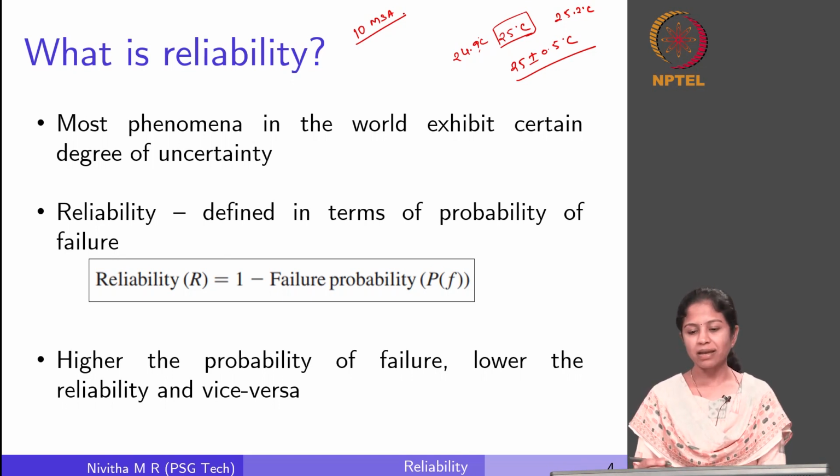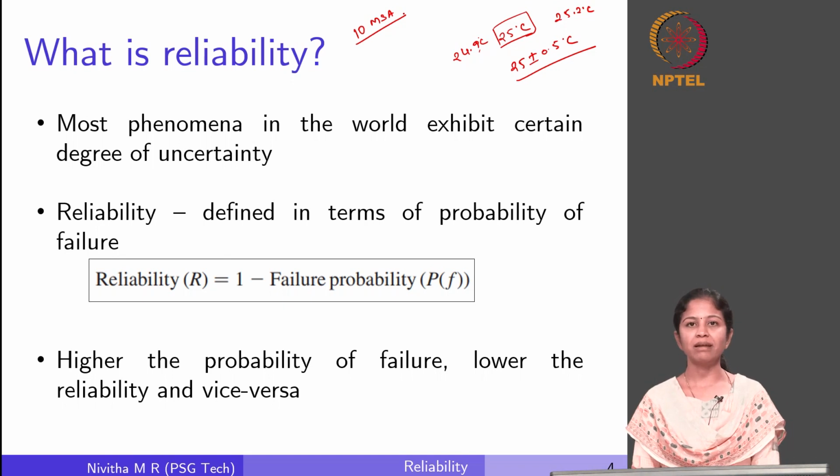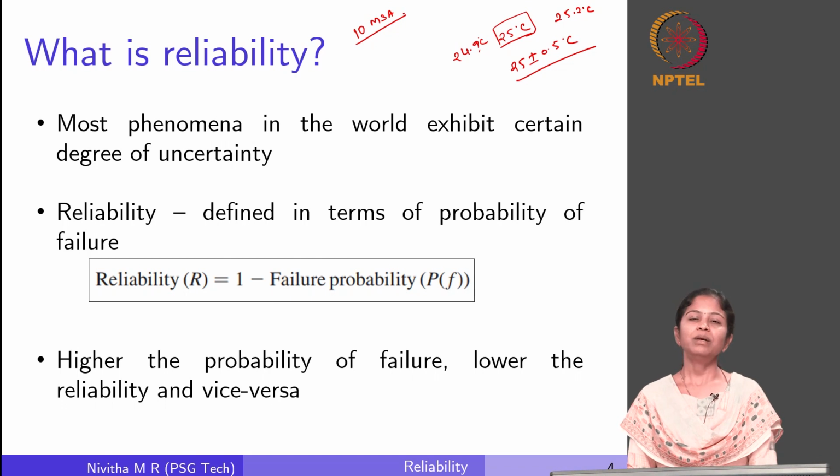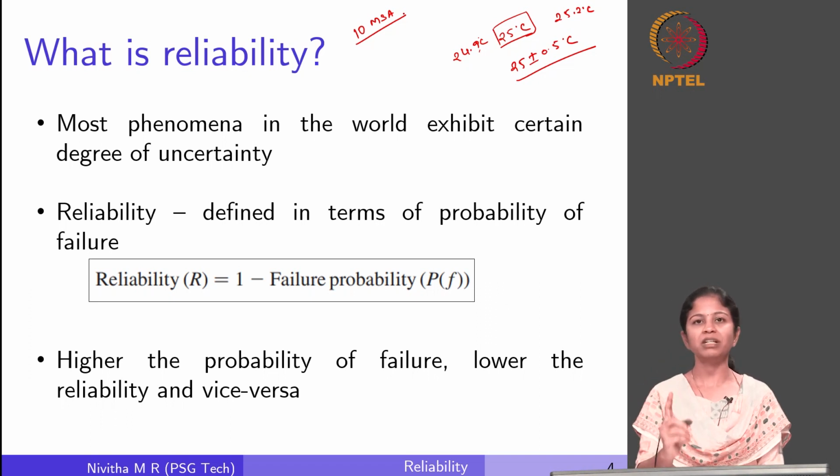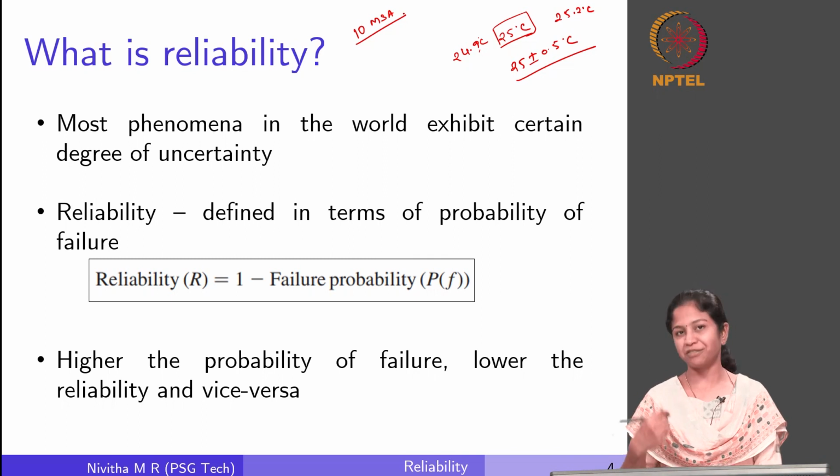Let us say I design my pavement to carry a load capacity of 10 MSA. Now, will it carry exactly 10 MSA? When I have the first repetition after this 10 MSA is exhausted, will it fail? We will define what failure is again, but will it fail?